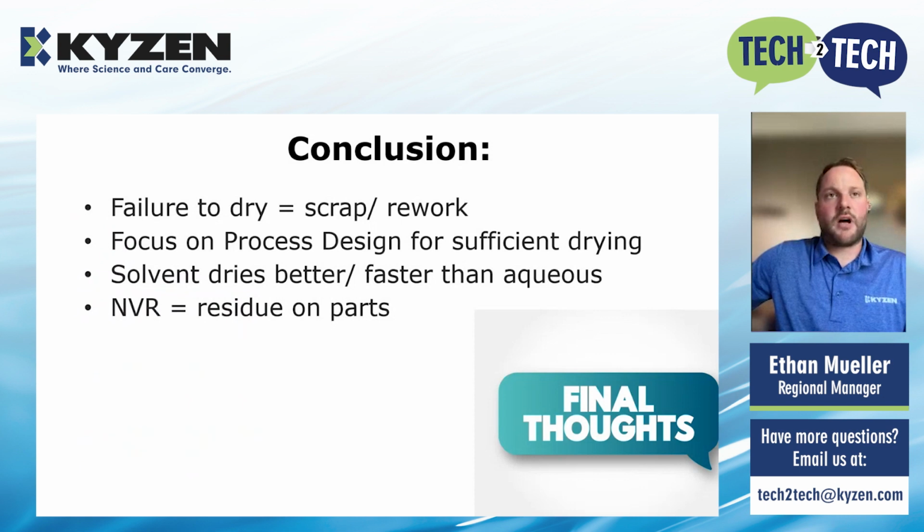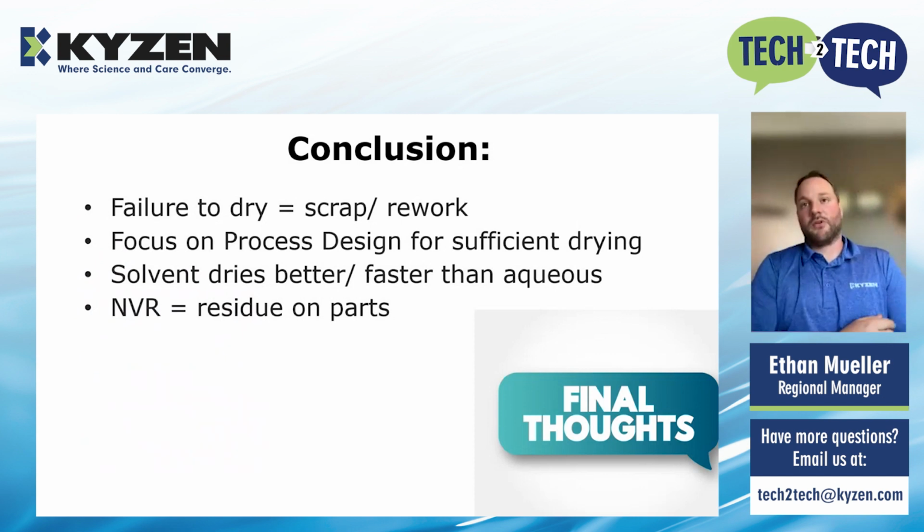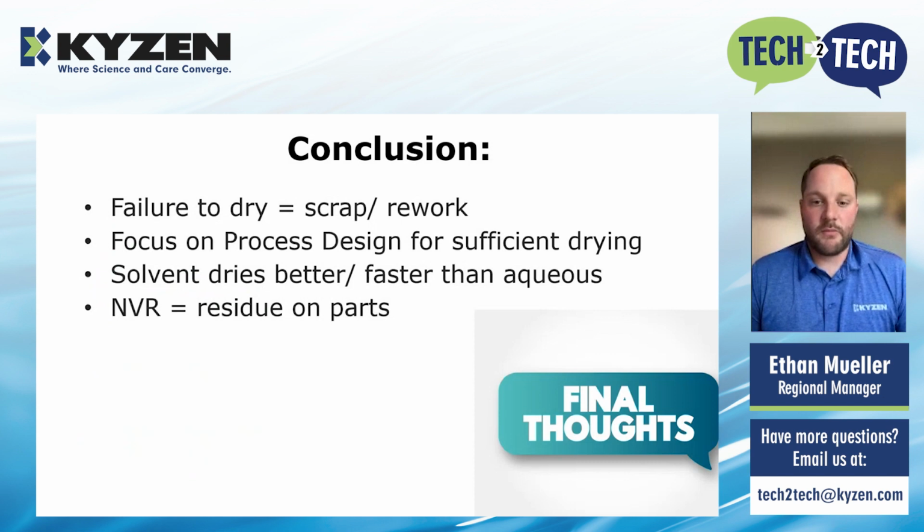When we're looking at a process or wanting to change a process, we want to focus on the overall design of things. There are a lot of levers we can pull with an existing process, and a lot of different processes we can choose from up front so that we're getting the right thing and it's matching our needs. Again, solvent is always going to dry better and faster than aqueous is. And NVR from our aqueous solution is going to result in residue on the part, which can lead to a failing